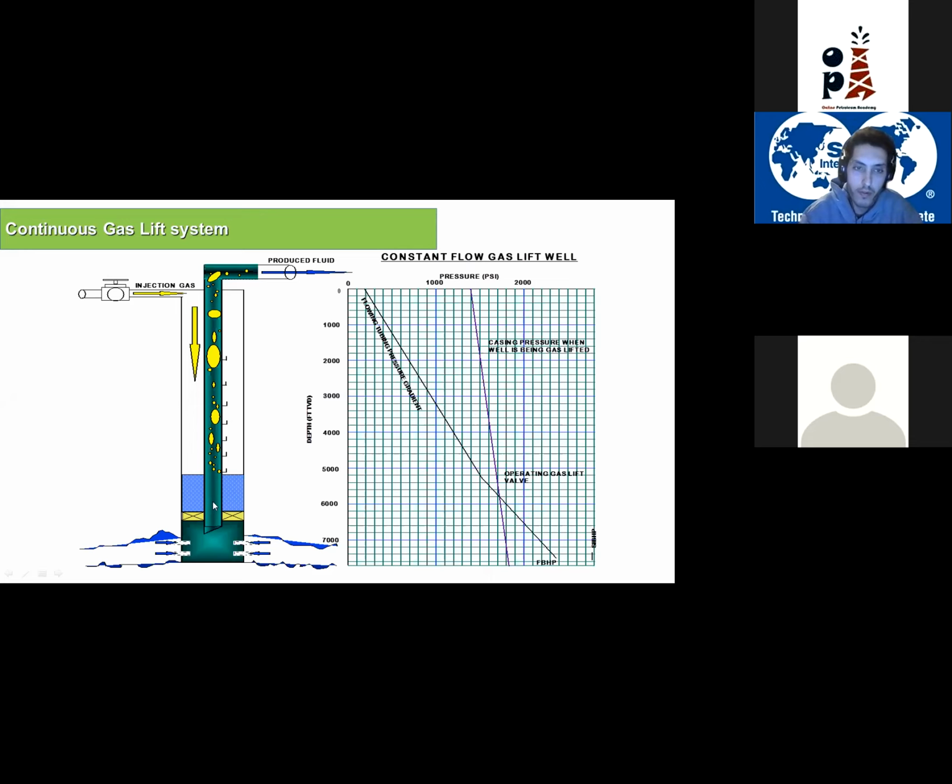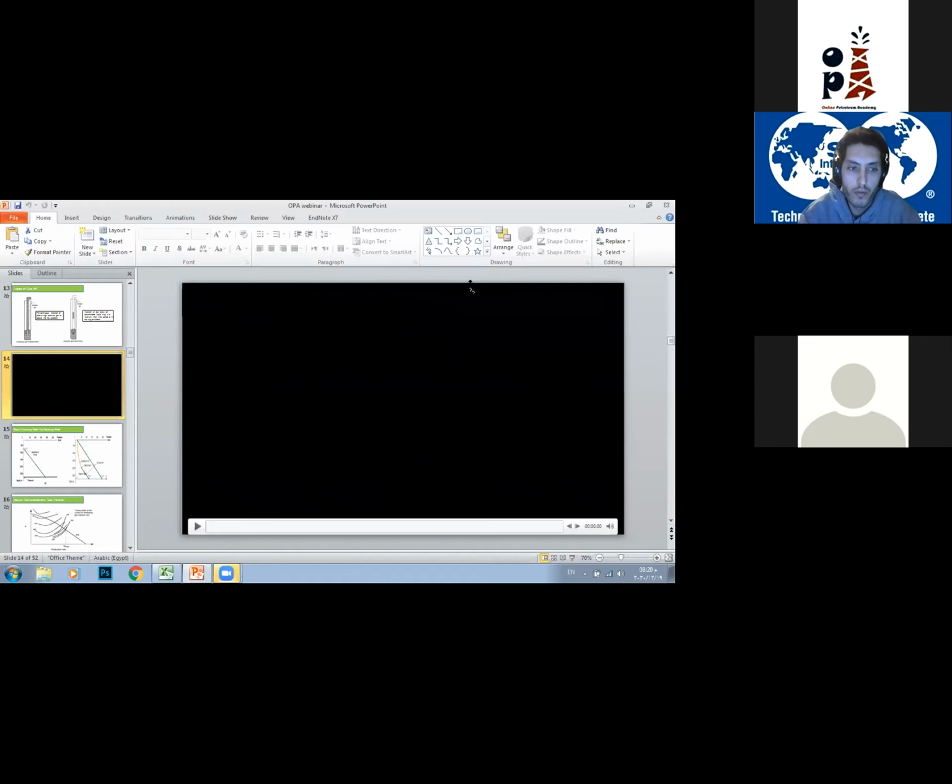When can you inject gas from here? If the reservoir pressure decreased, if the rate decreased, if you have lighter fluid. So for sure, when you have higher density fluid or higher density oil, it will affect your point of injection. So in this scenario, in order to inject at a deep point, either you have oil with acceptable density, or you have to have higher casing pressure here. Hope it's clear now. Yes, it's clear.